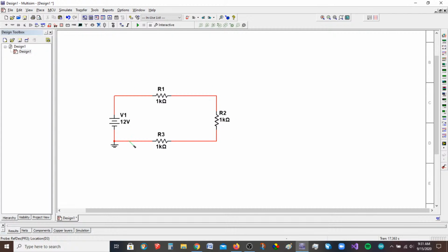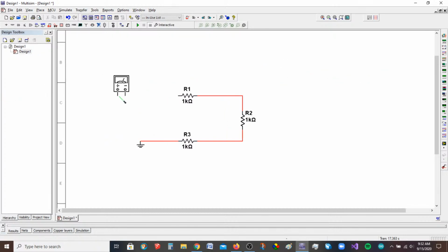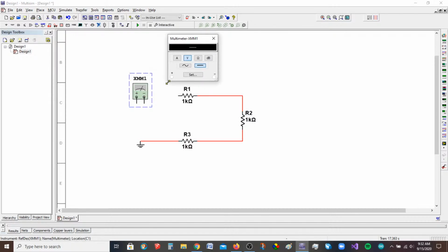Now, one of the things I mentioned in the resistance multimeter video is the fact that you can measure the total resistance in a circuit. So I'm going to get rid of this source just for a minute, and I'm going to come up here with my multimeter. Because resistors are not polarized, it doesn't really matter what the orientation of this is. It's going to measure the same no matter what, because you can't measure negative resistance. So I'm just going to connect the leads to the circuit.